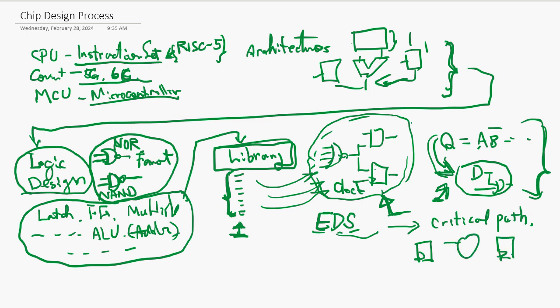There are many logic gates going through, and which path is the slowest determines the clock speed. So the slowest logic path is called the critical path, and nowadays software determines which one. Then you go back and see if you can improve the design to reduce this so the clock can be faster. So this kind of logic design activity is done by the logic designer.